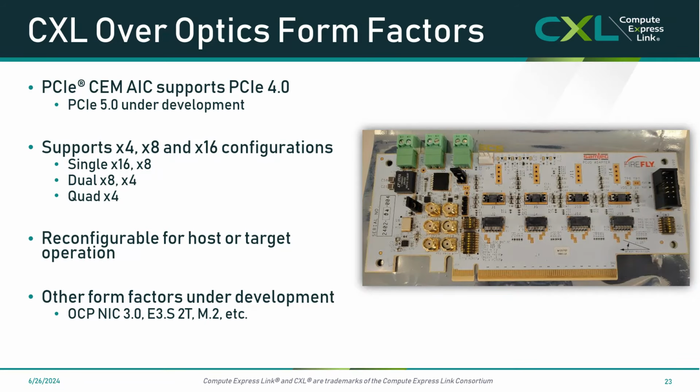In addition to the optical transceivers that support both the PCI Express signaling and the CXL protocol over the PCI Express, we are designing a family of industry standard form factor PCBs, which make enabling this functionality easier for the end market user. So the current card that was in the illustration was a PCIe CEM AIC supporting PCIe x8. We now have a solution that supports x16. We're working on, as I mentioned earlier, a PCI Express 5.0, CXL 2.0 optical transceiver that will drop into the same footprint. Hopefully, our plan is to have that available by the end of the year.